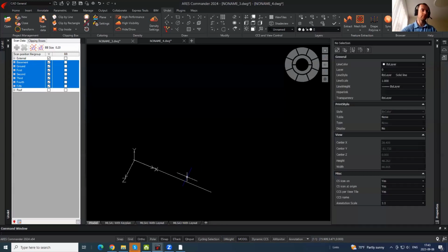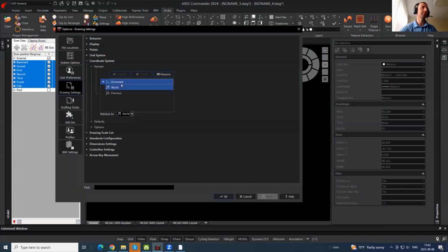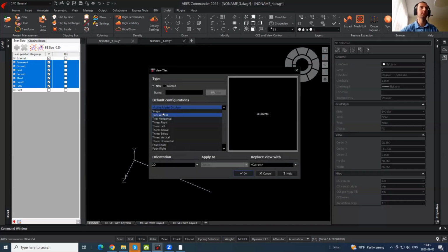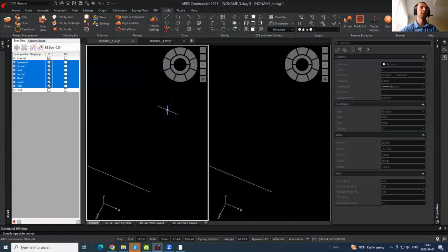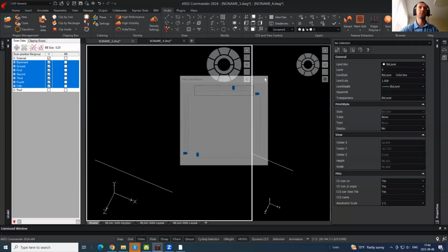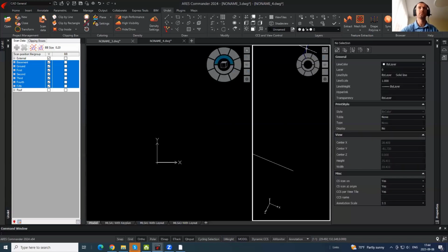I created the UCS, and later the same procedures: let's name it to save it, Section 1, for example. It will also be the same: create 2 viewports, one bigger, one smaller, one for the section view, another for the top view of the section.